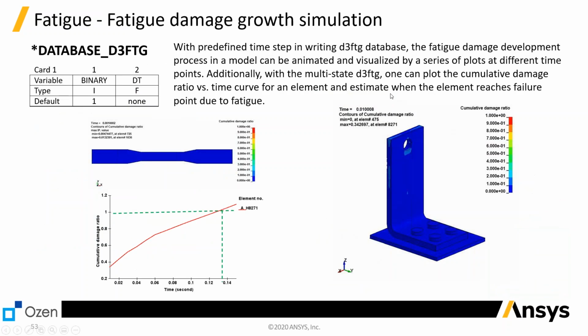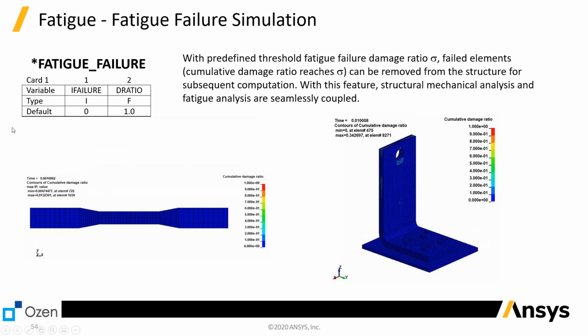Inside LS-DYNA, another feature added is using the card of database D3FTG. We can do fatigue damage growth simulation. I think we have some videos here as well to show, which will help to improve the fatigue performance using this card. Another useful card is the fatigue failure card, which will also help to capture the fatigue failure, as we can see here, inside LS-DYNA.